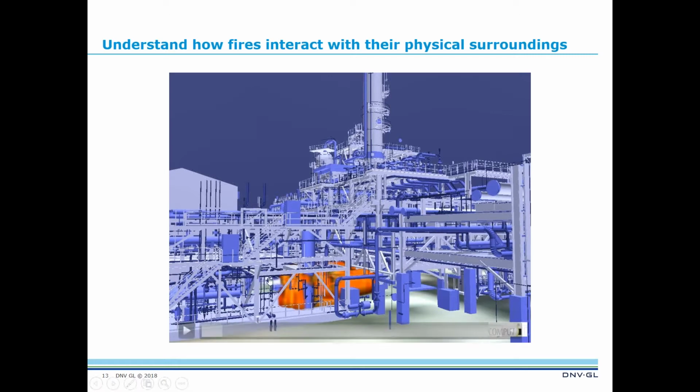So we have a horizontal gas release at the lower part of the facility coming from a high pressure vessel. So we have a high velocity jet in the horizontal direction. But this jet will now, due to the congestion, quickly impinge on some of the geometry. So the momentum of the jet will be broken, and within a quite short distance, this horizontal jet will transfer into a buoyant plume, which rises up inside the process facility.